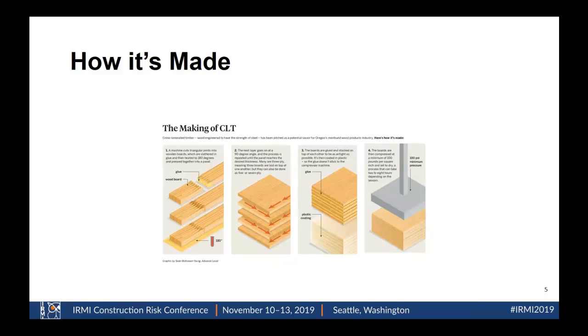Our panels were 4 foot by 40 foot long, so they used the splicing method with finger joints to create that length. Basically, it's what it sounds like. You're taking a 2x material, turning one layer one way and the next the other, and gluing them together, and through compression that forms a very robust product.